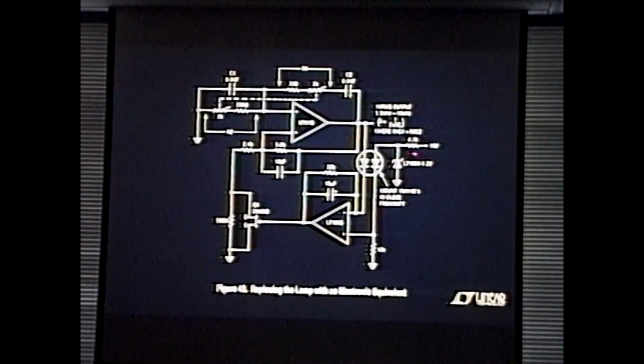We compare them with a voltage reference. We average, so this is going to set our averaging time constant right here. We average the difference between some DC reference and the positive output peaks of the sine through this big time constant. And then we use this FET to set the negative gain of the amplifier.